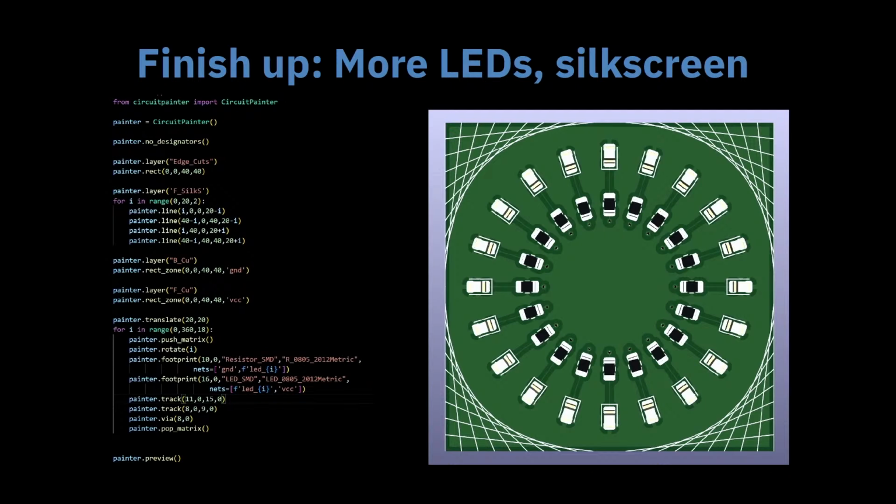For most of these ones, if I'm not making demo code, what I'll do is I'll either make a command line Python function that takes in arguments, so you can just type in like LEDs equals 20 on it. Or I started to do web interfaces for them. So you can do all of this, and you can get an SVG at the end. So I make a little Flask web server in Python that lets you choose all the parameters for your board, and then every time you change something, it actually calls KiCad, builds a whole board, and then gives you the preview in your web browser. So it's self-contained.